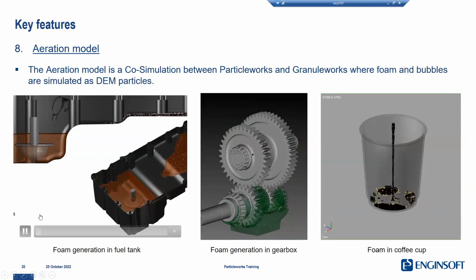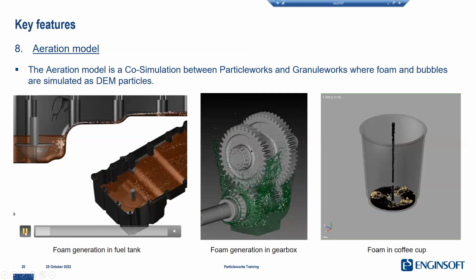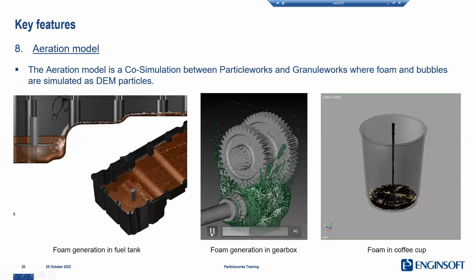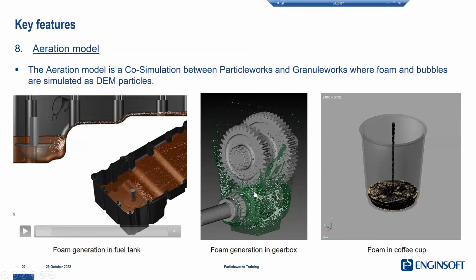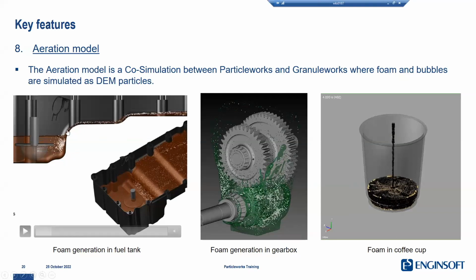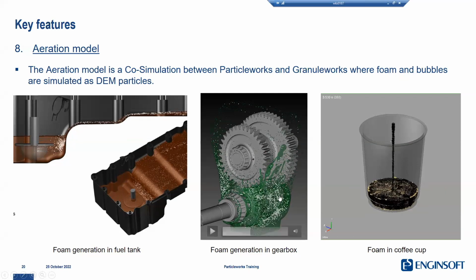And other features, as I mentioned, we can analyze also the bubbling forming inside the fluid due to some sort of interaction between the rotating elements or between the walls and the fluid. So we can analyze air trapped inside the fluid, and we can also have evolution of air bubbles inside the fluid phase.